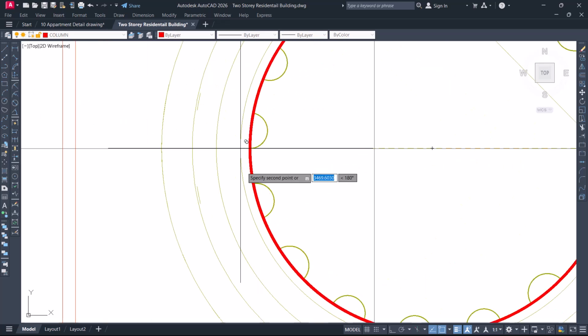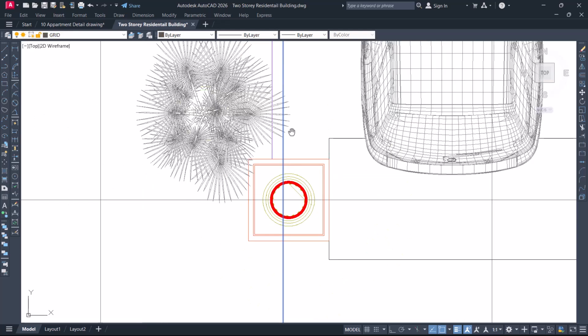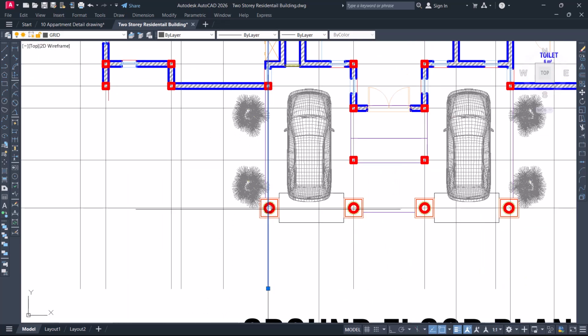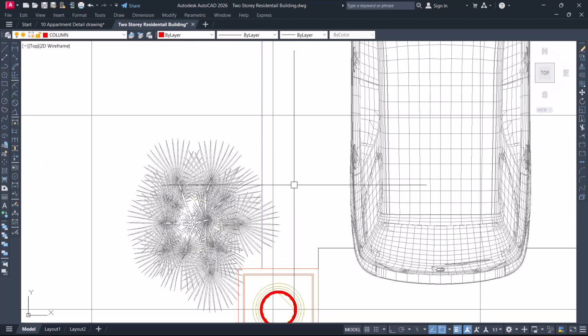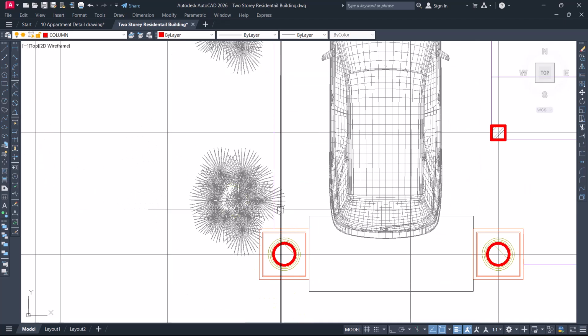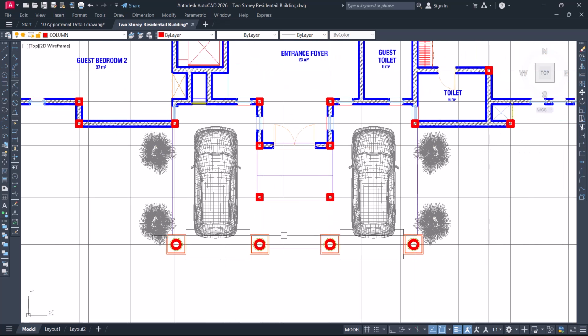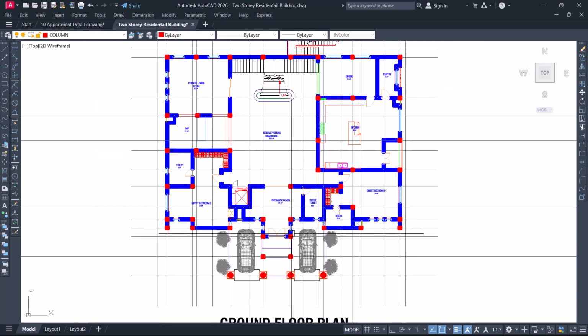The reason why I did this is that this grid line will serve as a roof beam center, right, between this column and this column here. Else, if you click another grid line here, you can see that the roof beam will not be transferring its load directly at the center point where we'll have this column inserted. Okay, that's fine. So with that now, let's look at what to do again. So with this now, we have taken into consideration all of the column points.